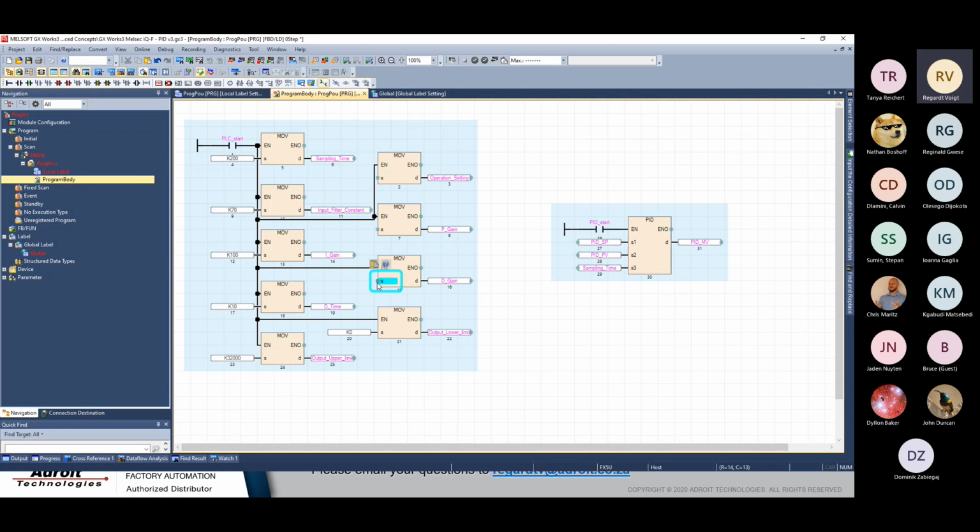Then my D gain. Remember what I said, if you don't want a very aggressive system, the D gain must be relatively lower than your I and P gains. So I'm going to make it K 200. Especially in an area where there's a lot of noise, although there's not a lot of noise in the simulator. So we don't have to worry too much about that.